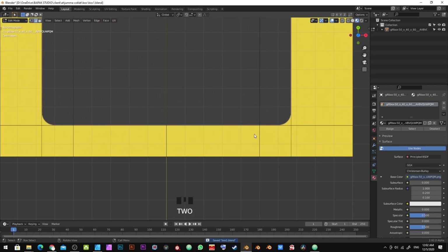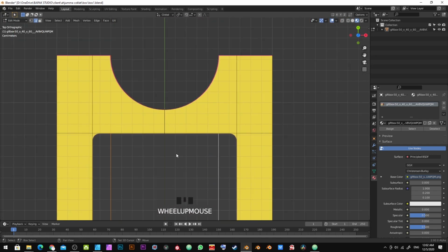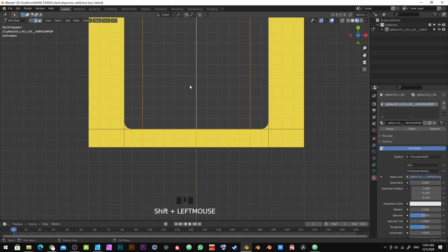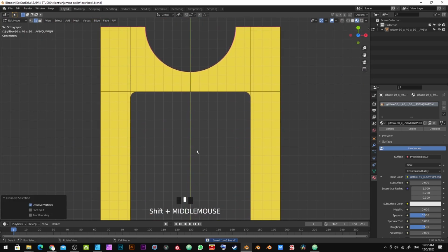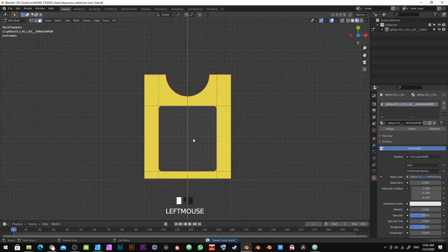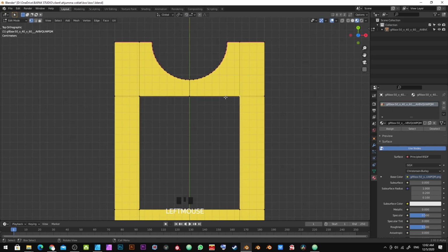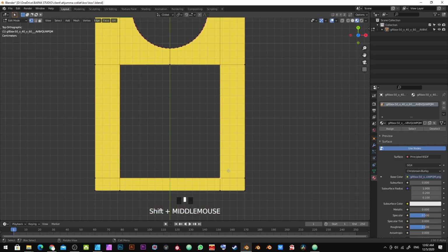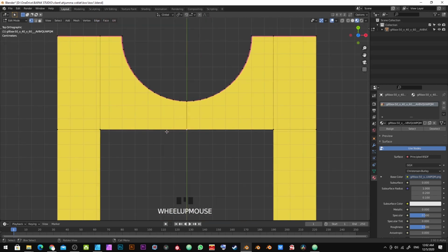So the next thing that you want to do is you remove the lines that are unnecessary, like these two lines and these lines and these middle lines. So press Ctrl X to dissolve it. So what you need to do next is set this face in the middle, delete the face and select all the vertex around it, the corner. If for this one you want to dissolve it, you can also just press Ctrl X.